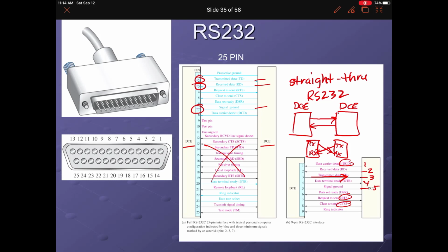So when it comes to this connection for RS-232 between a terminal and a modem, it was the modems, or the DCEs, that are looking after a transmit-receive crossover over the data channel. And in the telephone modem, it was frequency division. When it comes to fiber optic, it's a separate fiber optic line for transmit and receive to give you full duplex. But it's always the DCEs that are looking after a transmit-receive crossover. And so the RS-232 lines are straight through. So that's a straight through example.